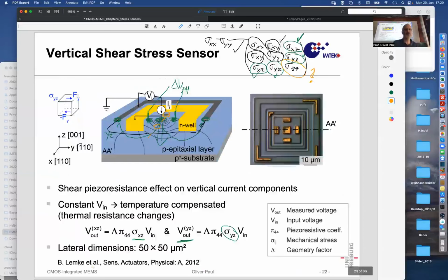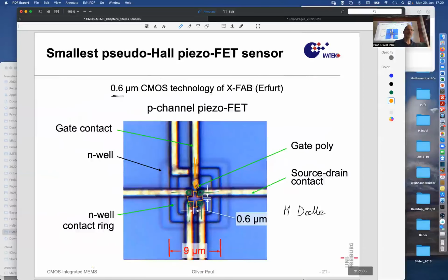So over those resistive devices here, the piezo FETs have the advantage of this built-in switch, the gate voltage. If you have an array and you would like to read out one device, you switch the gate voltage of that one device to inversion, and then the current can flow, you can do your measurement, and all the other ones are highly resistive because the gate voltage makes this device operate well below the threshold, and therefore no current flows.